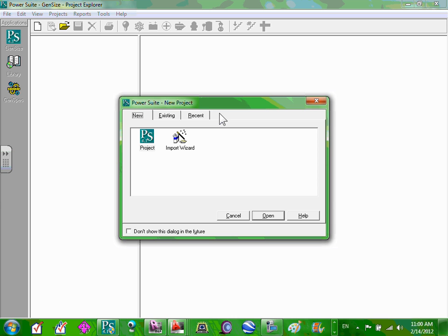Cummins make generators, medium and low voltage generators. And what you guys are going to be doing is sizing a generator for the commercial building. We have a backup generator, 100%. Our gen that we size for this building is going to back up this generator 100%. I know the service that we have is a 500 amp panel. You could easily take a 500 amp panel, multiply it by 208, multiply it by 1.73, and get the kVA. That's not how we size generators, though.